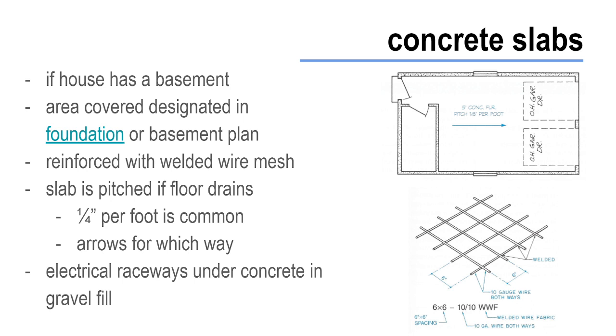When there might be any confusion also about which way your slab is pitched, there'll be an arrow drawn to show the direction and the way the water is running. So in this example, the water is running that way, so it goes out those overhead doors.